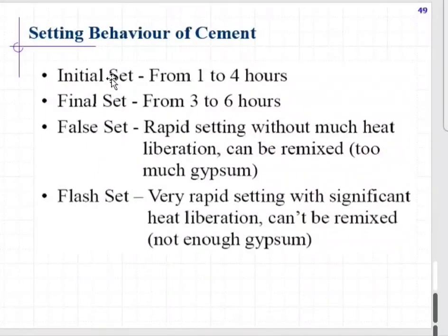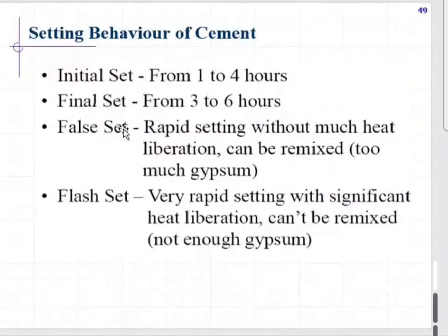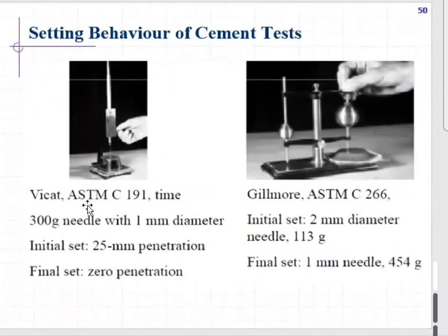Then comes the initial set. Initial set is from 1 hour to 4 hours. You can write down as per the standard, it is actually 45 minutes to 4 hours. Final set time is 3 to 6 hours; it has gone up to 6 to 8 hours also. False set and flash set, I have already given you the definitions in the previous phase. False set, if you remix it, can be remixed. But flash set cannot be remixed. You can remember it like that.